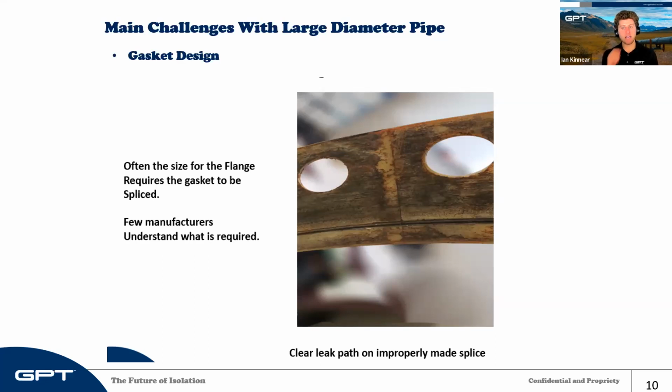And it is kind of a science, and the design of this is really important. You can see here that this isn't a good design for segmenting. A leak on these occurred right at that joint because that surface is uneven. The joint's not at a proper length, and you can see it's actually cutting right through the steel. So there's just a leak path right at that segmentation.